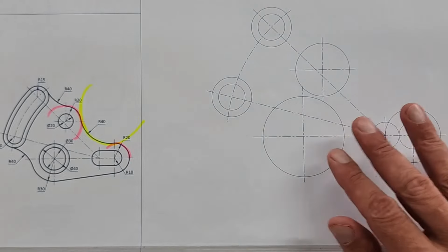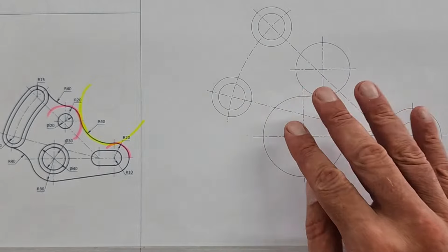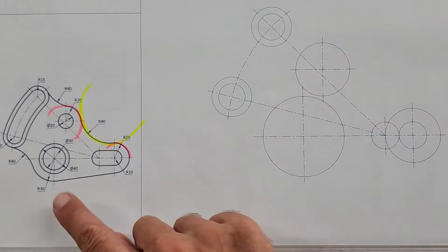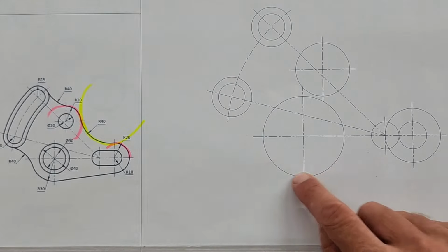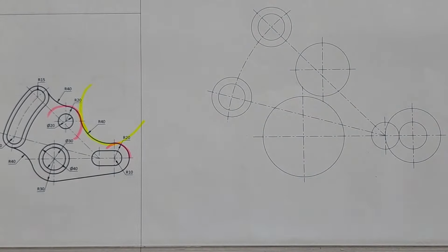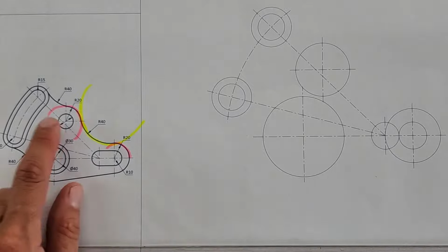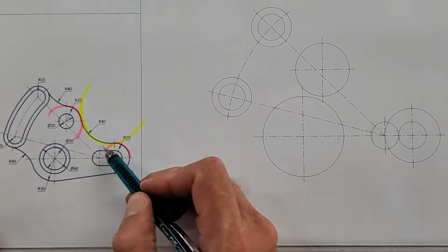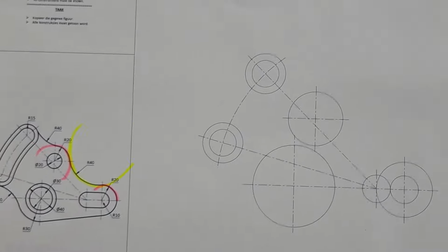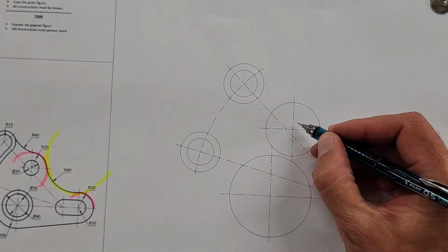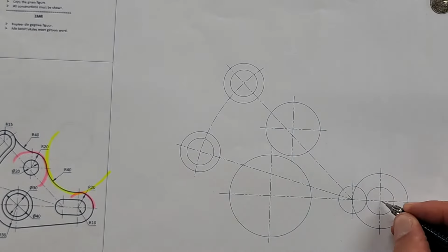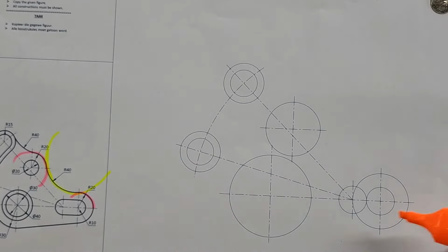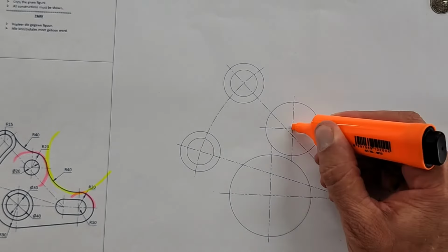Okay, so we're now going to begin by using what is given here on the drawing. And we're going to see if we can get this drawn. Luckily there is quite a number of pieces of information already given. So let me take you step by step. Let's start here on the pink and the yellow that I've already mentioned. So we have here the first radius, that is radius 20. Yes or no? Yes. And we have another radius of radius 20. And I'm working with center points. I'm going to be using these centers.